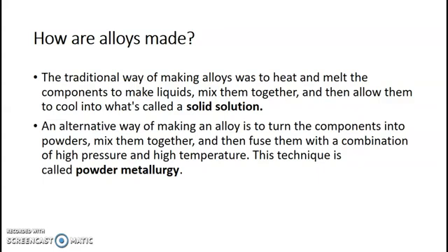The next one is powder metallurgy, in which the components, the base metal and alloying metal, are made into powders, and we mix them together and fuse them into a material by means of high pressure and temperature. That is the process of powder metallurgy. So these are some of the basics of the constitution of alloys and how solid solutions are formed.